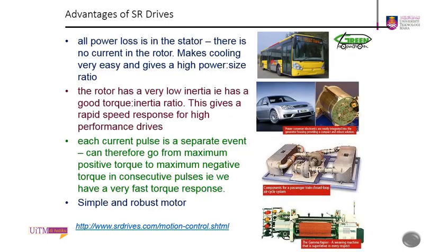Other advantages: all power losses are at the stator, so there is no current in the rotor, and thus it makes cooling very easy and gives a high power to size ratio. The rotor has very low inertia and a good torque to inertia ratio, and this gives a rapid speed response for high performance drives.